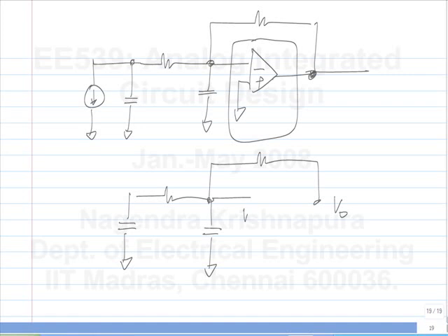V out to the input of the op amp. What is the phase shift? It is minus 90, right? Isn't it? So this probably won't affect the phase at all, but this is going into a capacitor. At high frequencies, all of the current will go into the capacitor. Okay. So the phase shift around the feedback is 90 degrees again. It's exactly like if you didn't have any of this.